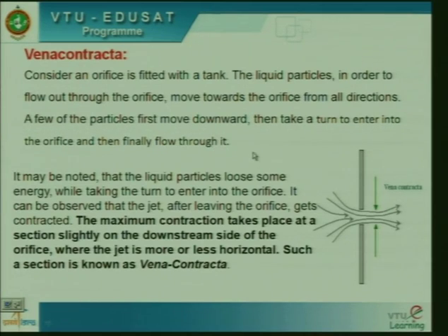Suppose this is one side and this is the bottom side. The fluid particles slide smoothly along the boundary, flow along the bottom, and finally move along this boundary and get out of the orifice. It may be noted that the liquid particles lose some energy while taking the turn to enter into the orifice.